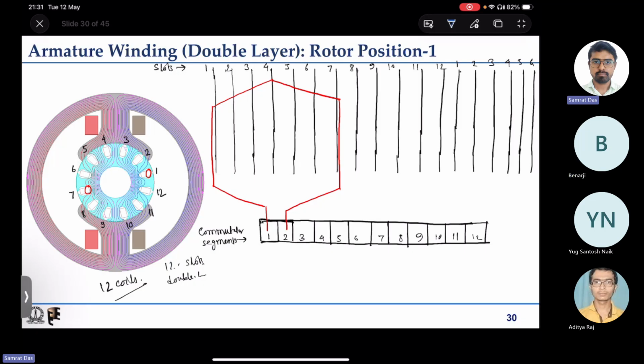Finally, when you are making winding, say you are starting with coil 1, one side should be at the top, another side at the bottom. Say you place the bottom one, but can you place the top one first? No, you have to keep it outside only. Only after your bottom one is put can you put the top. That's all.